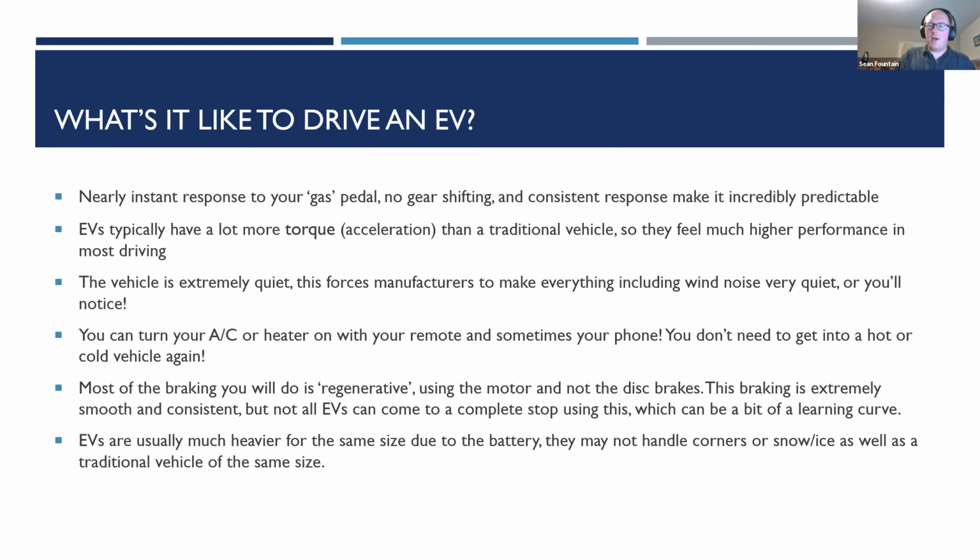Tesla, I don't know if they were the first, but they were the most prominent to introduce what they call one pedal driving, which is that the regenerative braking provides almost as much braking as the vehicle can possibly sustain, right? So that's a lot. That's like you hit the big brake pedal really hard, and it does that when you let the gas pedal off. And they tune it so it's not immediate, so it's not like an emergency braking situation. You let it off and it will keep increasing the braking if you keep your foot off the pedal, and it will bring the car to a complete and pretty firm stop. It'll even bring the car to a fairly firm stop if you're lightly pressing the pedal.